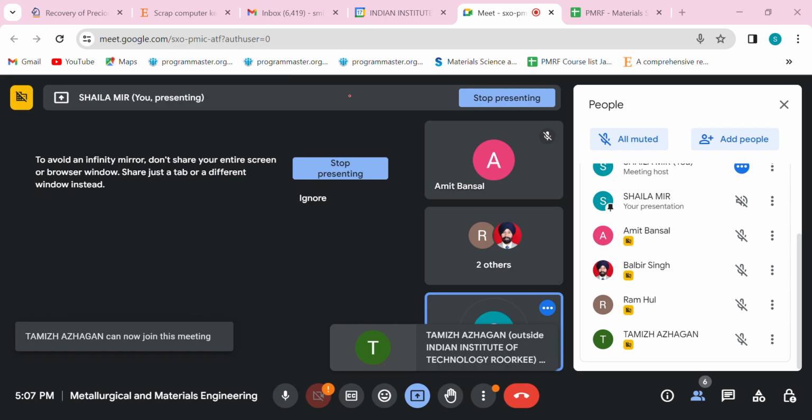So it should penetrate into the discontinuities, and then that will pull out your dye for better visibility. I think option A is also right, but the function is not only for providing a contrast but also to pull it from the crack or defects and make it visible.